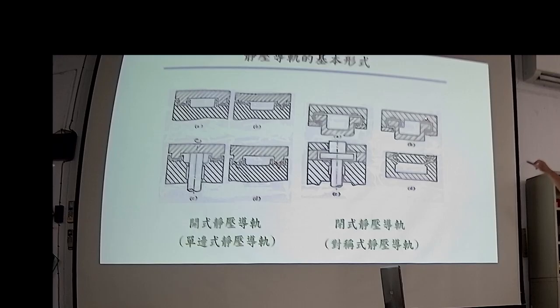We have two bearing recesses in one diagram, and in another diagram we have four recesses. So, in the radial direction, here you have two recesses, here you have also two recesses. This is a closed form guide rail, hydrostatic guideway system design. Okay.